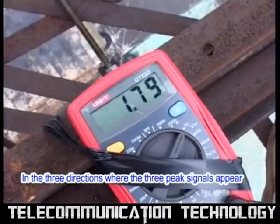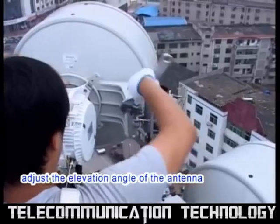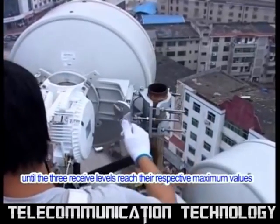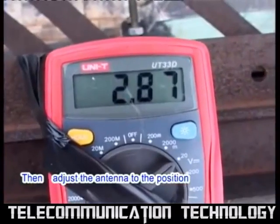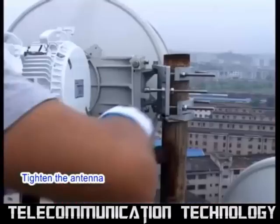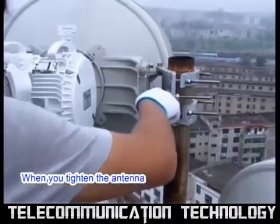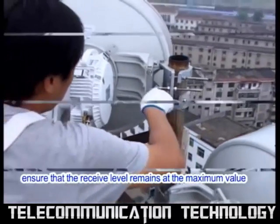In the 3 directions where the 3 peak signals appear, adjust the elevation angle of the antenna until the 3 receive levels reach their respective maximum values. Then adjust the antenna to the position where the receive level is the highest of the 3. Tighten the antenna. When you tighten the antenna, ensure that the receive level remains at the maximum value.